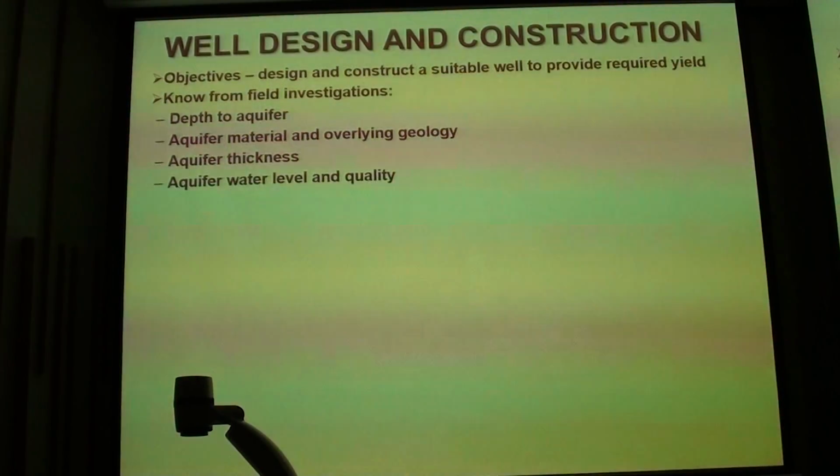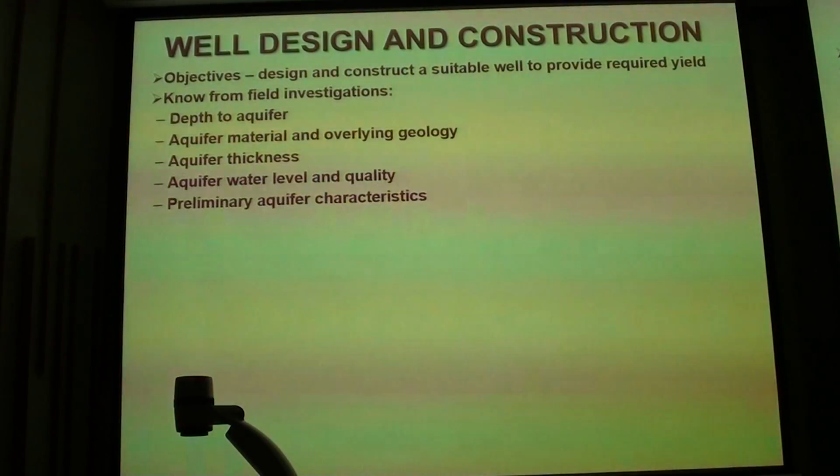We've got an idea of the quality of the water with those preliminary tests, but they're not always that great. They generally come up with high iron and manganese levels simply because of the drilling process. The development doesn't completely clean it out, because we've only done that for 2 hours. But there are safety levels, and generally if you get high iron and manganese levels, they will drop through time with pumping, so they're not a big deal. But it's the lack of things like boron and sulphur and arsenic and all those nasties I talked about last time. If you haven't got those, most likely going ahead will be good. We've got the preliminary K from the displacement testing, so we know it's okay.